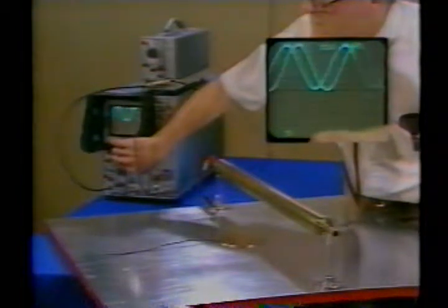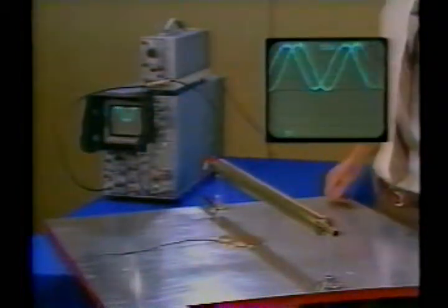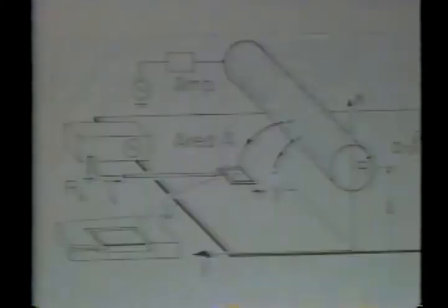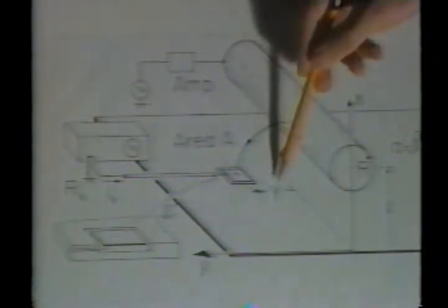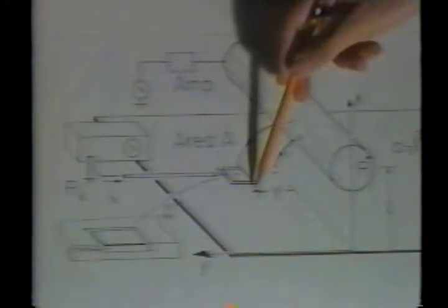The signal is largest directly under the conductor, trailing off to zero as the probe is pulled away. As the probe is moved out from under the conductor, the lower scope trace shows the charge induced on its surface decreases.